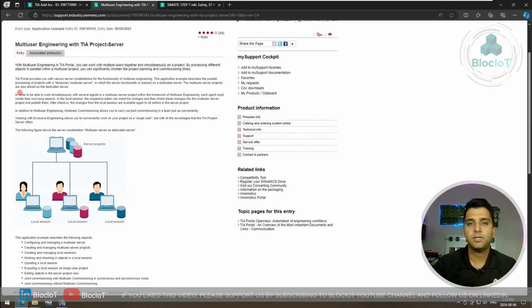So we can use VCI for version controlling of our PLC program. But what if someone wants to track changes in their HMI or SCADA project? They cannot use the VCI at the moment. Maybe in the future at some point Siemens adds that capability to VCI, but at the moment it is not possible. So you cannot use VCI for managing your HMI SCADA project.